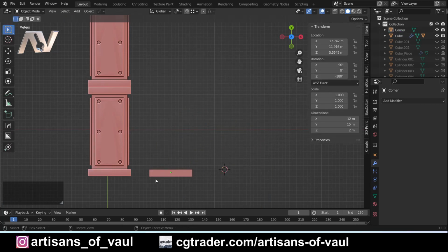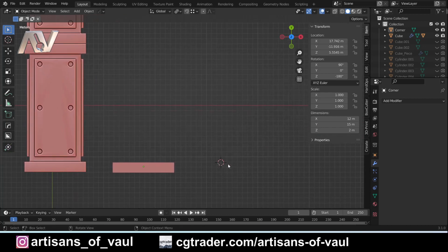So part of the design brief here is that everything in all dimensions shouldn't ever be more than 25 millimeters, so 2.5 centimeters, approximately an inch. Now that's not necessarily a problem. All we need to know is, instead of guessing where we're going to put the cursor, which is what the spin tool rotates around, we need to put the cursor exactly where we want to be.